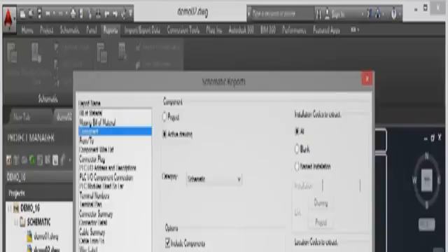We will freshen the project database, and we will leave the installation codes and location codes in this time. So I click on OK, and there's my report. Before I actually start editing my report, make sure that you've got everything you need. So we've got tag name, component, subquantity, manufacturer, and catalog number. So that's all in there.